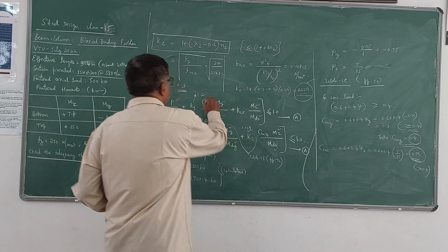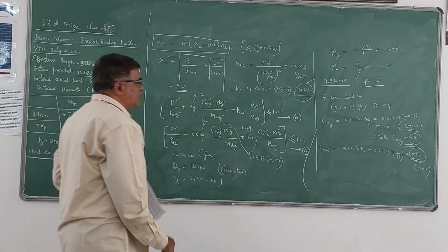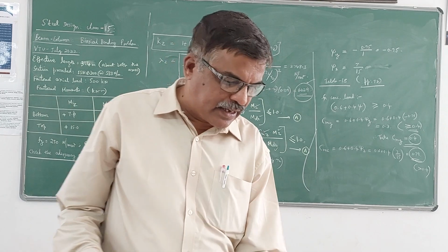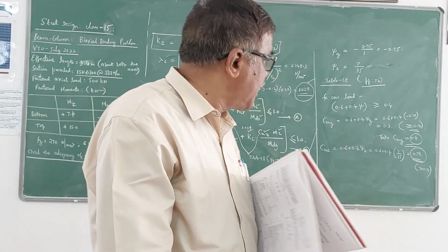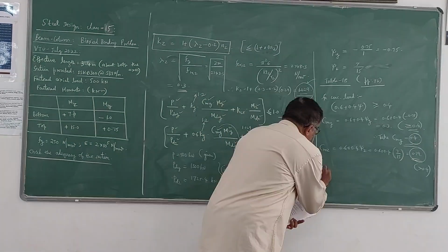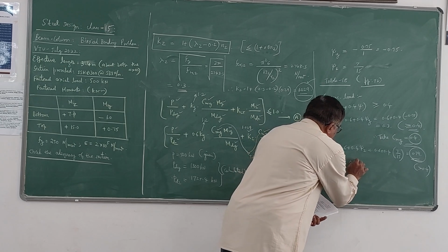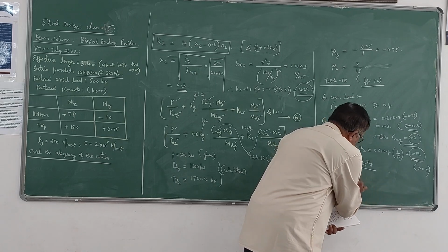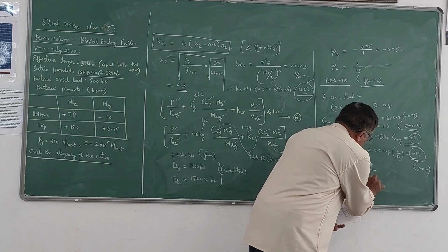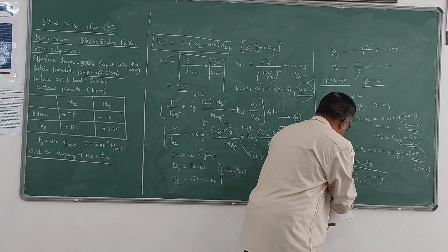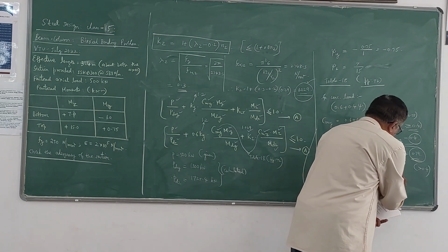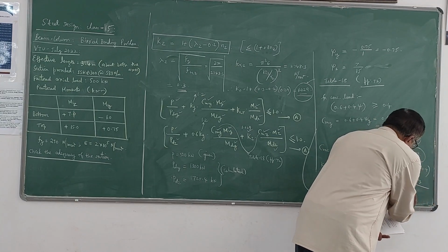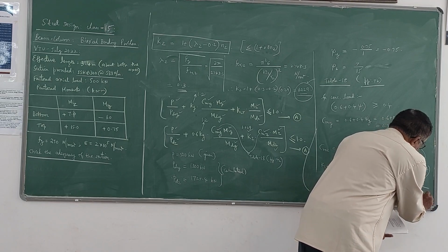So now these two we got. CMY we got, CMZ also we got. Now the last value we need is the KLT value. For finding KLT, we have the expression on the same page 71. So KLT is equal to 1 minus 0.1 lambda LT into NY divided by CMLT minus 0.25. Of course, there is a check for this. The check is it should be greater than or equal to 1 minus 0.1 NY divided by CMLT minus 0.25. So this is the check.